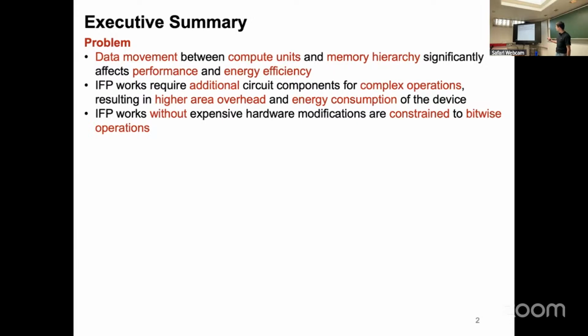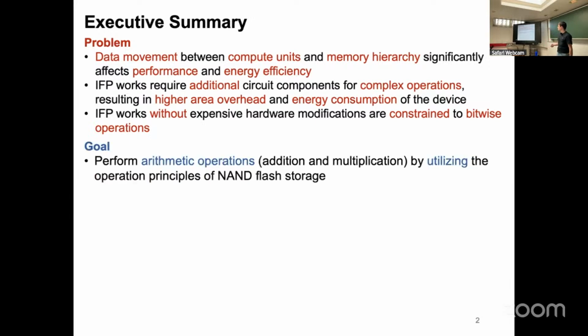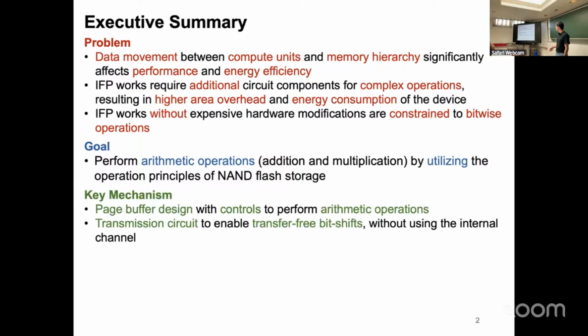The second approach, which we are going to focus on today, is in-flash processing that works without expensive hardware modifications. However, it is constrained to bitwise operations only. The goal of Aries Flash is to perform arithmetic operations like addition and multiplication, utilizing the operation principles of NAND flash storage. They leverage a page buffer design with controls to perform arithmetic operations, and also propose a transmission circuit to enable transfer-free bit shifts without using the internal channel.